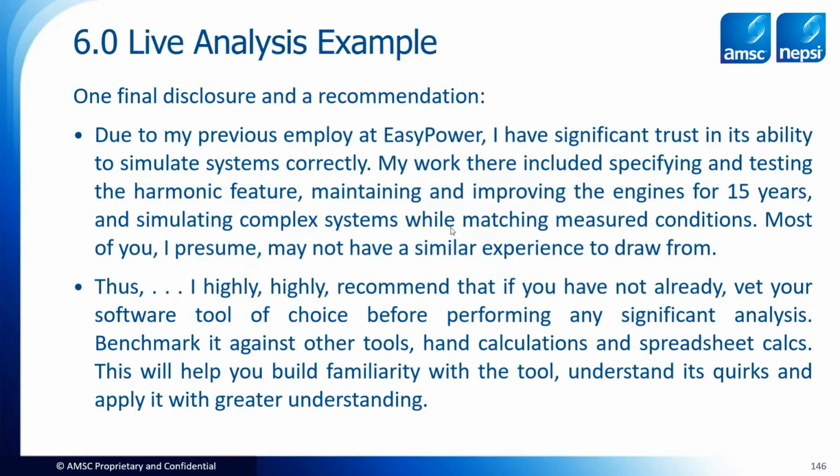Most of you, I presume, may not have that same experience to draw from. So I highly, highly recommend that if you have not already, you vet your own software tool of choice before performing any significant analysis. I really recommend this. Benchmark it against other harmonic analysis tools, benchmark it against hand calculations and spreadsheet calcs, and against what you expect to see out of that tool. This will help you build familiarity with it, understand its odd behavior, and apply it with greater understanding.